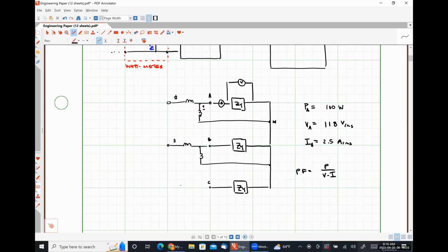Throwing, and let me make sure I'm remembering to do the polarity of the coils. Once again, that is important. And we'd also obviously have to put in a current meter and a voltmeter for each of the 3 phases as well. And then from there, we could figure out power factors and all that kind of good stuff.